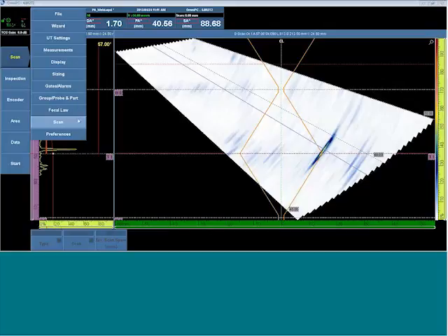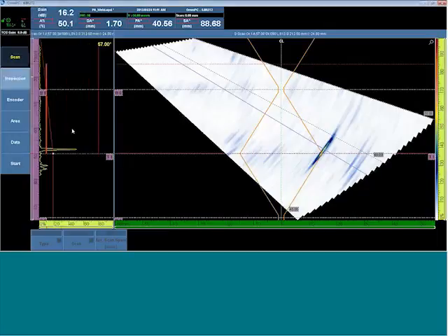the focal laws. So one of the things we do to convert this to a recorded inspection is first we'll set the scan type as a one-line scan on an encoder. When this happens, we'll see the small icon at the top left corner of the screen change from a clock to an encoded inspection.